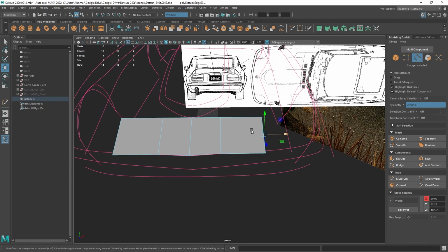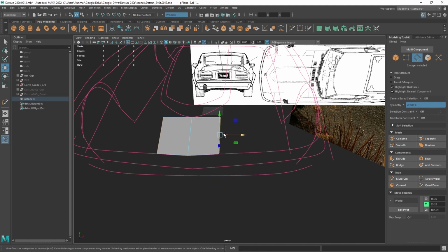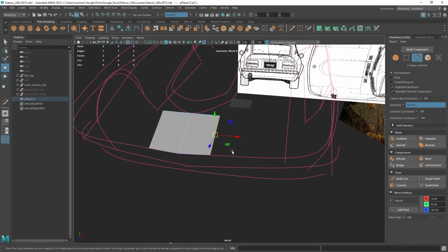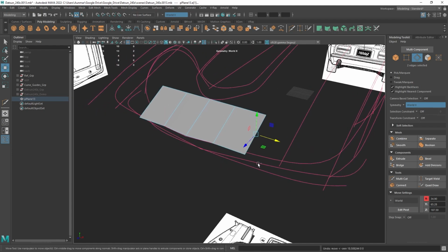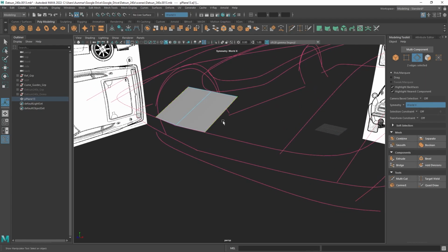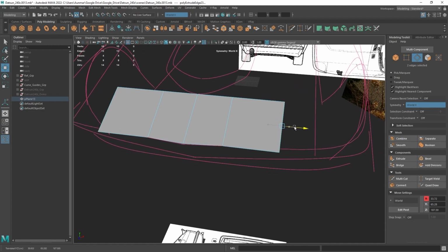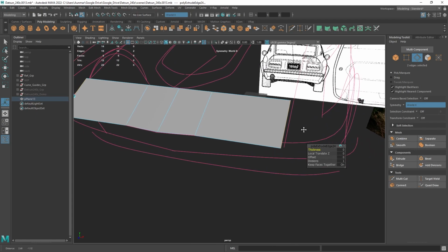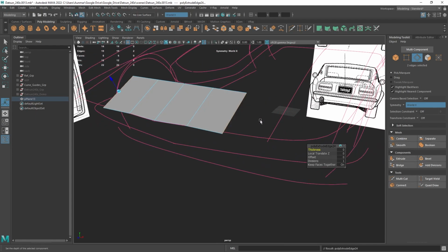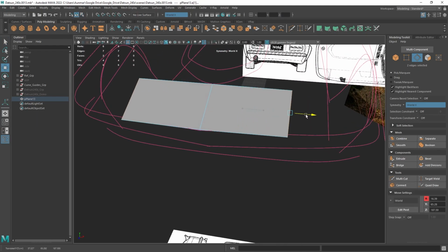We're using this edge copy method. By simply holding right click, jumping to edge mode, then holding shift and moving with the move tool, so just grab your move tool with W, hold shift, and then move. That's just simple edge copy. This is the same as using Control E to extrude an edge, and you can also just use the shift move, and that's going to be completely fine. It is obviously a bit faster than using Control E or using extrude here as well. Okay, so I'll undo that, get back to my base, and we're just going to move things into position.